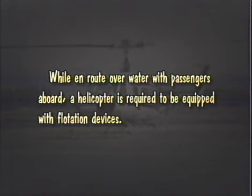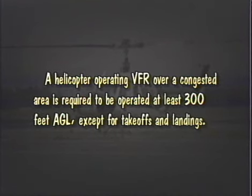While en route over water with passengers aboard, a helicopter is required to be equipped with flotation devices. And finally, a helicopter operating VFR over congested area is required to be operated at least 300 feet above the ground except for takeoffs and landings. Well, that's it. We've covered a lot of territory.